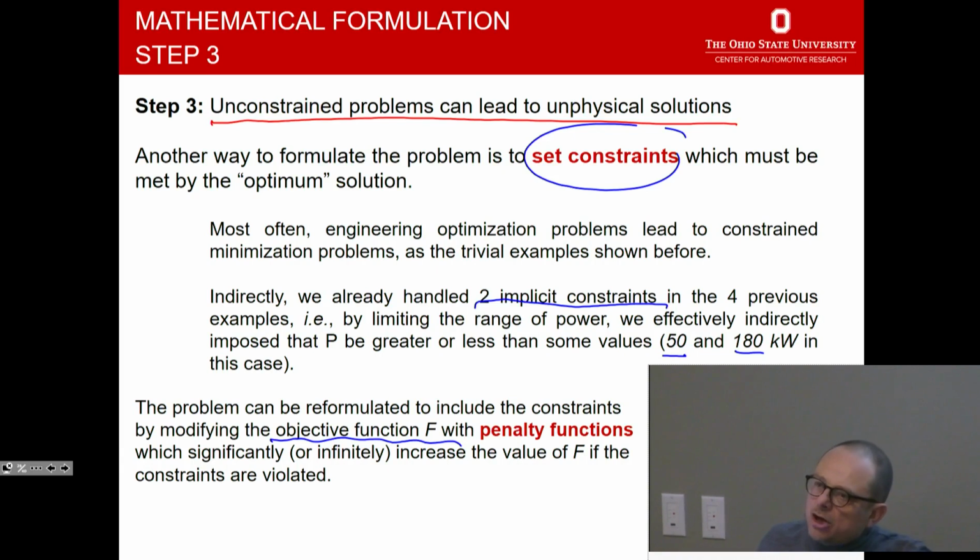So instead of making the 0 to 60 acceleration time one of the elements of the cost function around which you optimize, you could impose it as a constraint and say, I'm not trying to minimize the 0 to 60 time. I just want to be sure that it doesn't violate some limit that I'm going to pose, which is a way of saying I want the vehicle that is going to have the best fuel economy, but it must accelerate at least as fast.